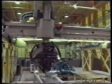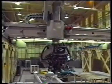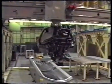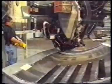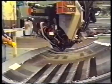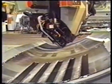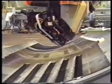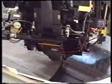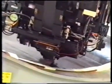Automatic tape laying machines are programmable gantry-style machines having a Y-axis crossmember, sliding on X-axis ways that supports a multi-axis tape laying head. The head has a spool of paper-backed unidirectionally reinforced tape and cutters to cut the tape without cutting the paper, which is retrieved on another spool. The head also can heat the tape if necessary to develop tackiness.